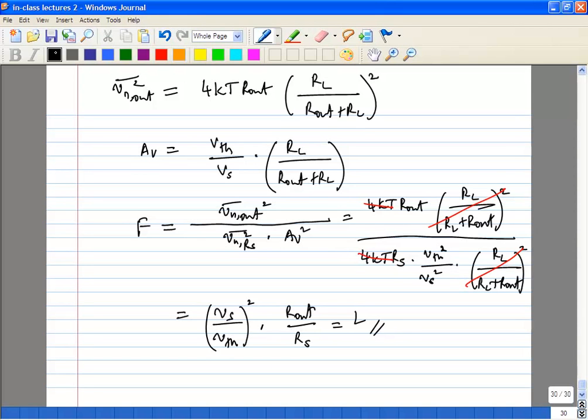And how do we know that? Because if you look at the cascade, the overall noise figure is the noise figure of the first stage plus F2 minus 1 over the gain of the previous stage. So first of all, the loss adds directly as noise. Second thing, the noise figure of the LNA also goes up, because now instead of a power gain, it's actually a loss. Two things happen. So it's a major problem, and you need to minimize the loss of these filters as much as possible.